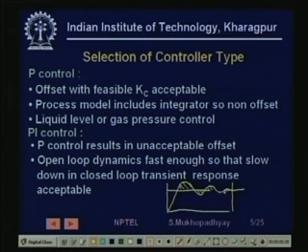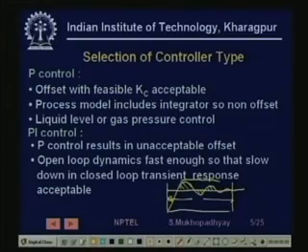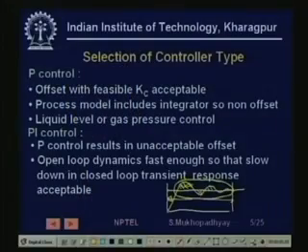So obviously you will find that they are acceptable when, see, every time there is a set point change, such an oscillation will actually result. It will die down, and then from then on, after it dies down, the loop will exactly achieve zero steady state error. So if this interval over which there is some error is actually small compared to the frequency of set point changes, then you can say that okay, even if during this period I have some error and my control performance is maybe affected, if I have an integral error criterion, then it will be less affected because this positive error is going to cancel this negative error. But even then I am able to tolerate this much of error because it is going to die down reasonably fast for me, and then it will stay on for a long time, right?